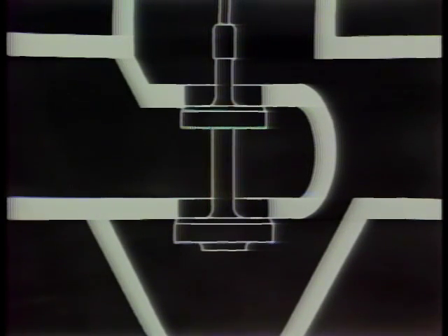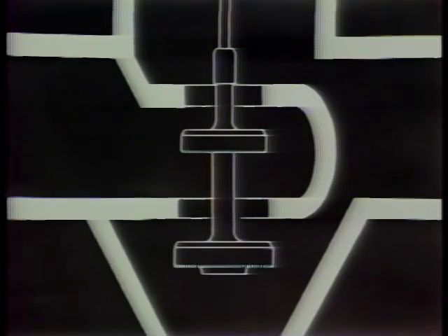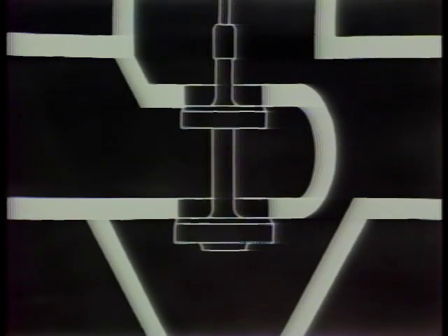Actually, practicality demands that the top seat be slightly smaller than the bottom seat for ease of assembly and disassembly. This prevents the valve arrangement from being perfectly balanced, but doesn't have much effect on the regulation curve. Tight shutoff is virtually impossible for a dual-seat valve because of manufacturing constraints.